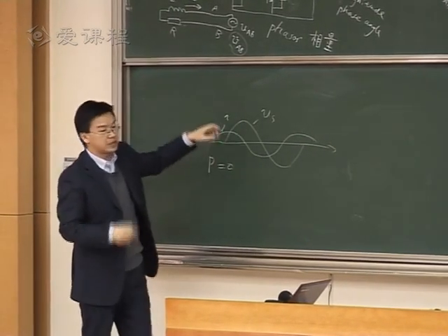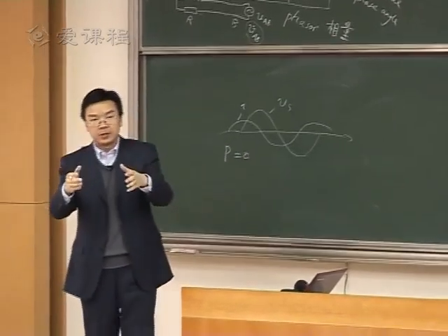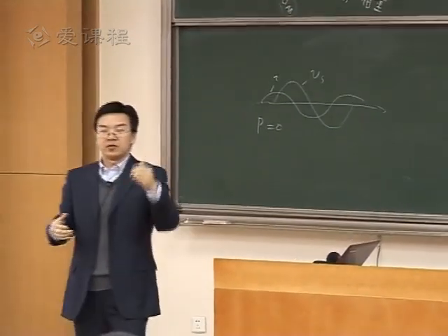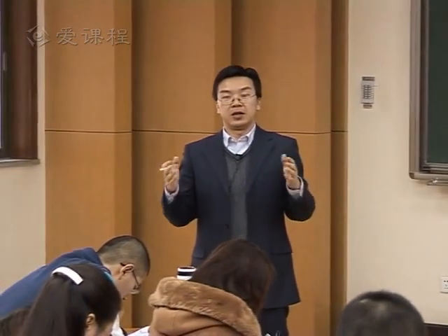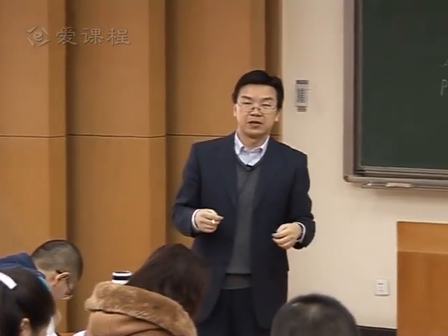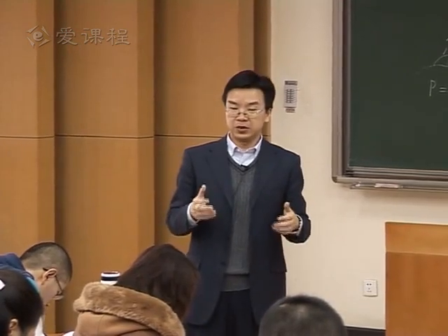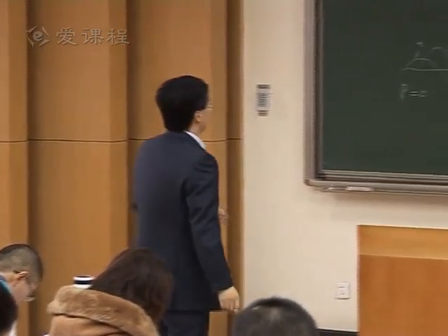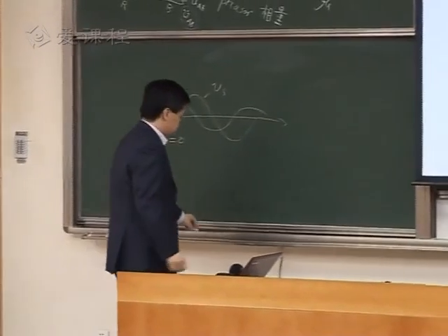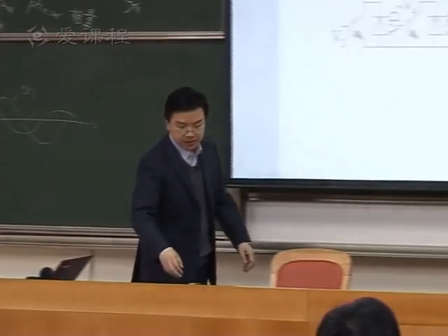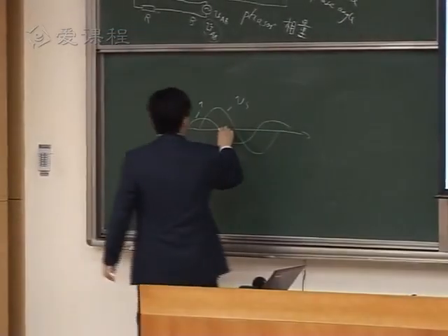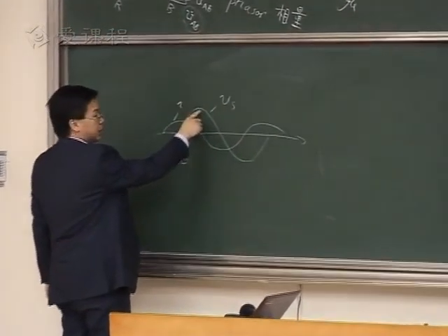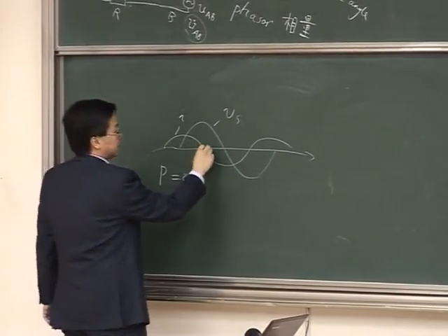So in this case, we are absorbing reactive power from the grid and absorbing no active power, only absorbing reactive power. You can also control this current's phase angle so that I is delayed to Us, or lagging Us, by 90 degrees.